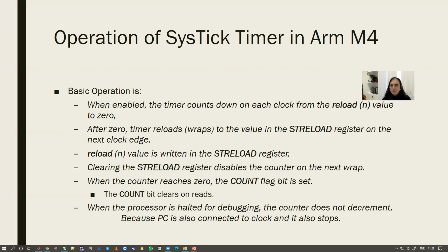And actually, since we have to set some control registers to make it work, it needs an initialization procedure, because as you all know, if you want to make a device work on an embedded system, it could be an external device or an internal pad like GPIO or an internal circuitry like timer, whatever. What you do is you set the necessary control registers once at the beginning, and that procedure is called initialization. We have to make a timer initialization. So let's try to make sense of what the steps of these initializations are, one by one.